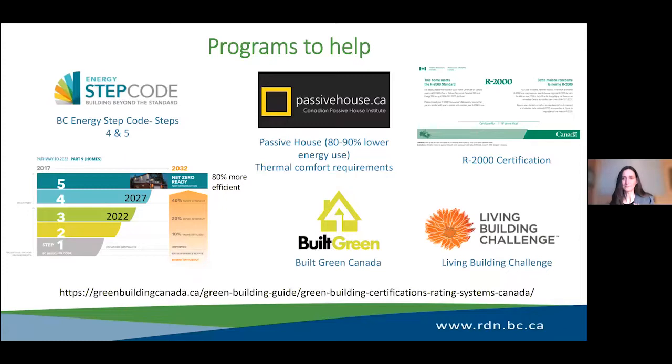So local governments can opt in to whether or not they implement it. It is active in some areas. I know Nanaimo, I think the Municipality of North Cowichan, and Lantzville have enacted parts of Step Code, but over time it is supposed to be brought into the BC Building Code, so it applies everywhere over the next 10 years or so, eventually requiring net zero ready homes by 2032. So we're looking for a scaling up over time.